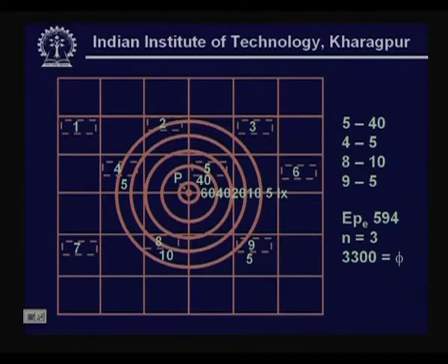Now, from the manufacturer's isolux diagram, we place it. Incidentally, the picture shows the calculations being done at the center of this diagram, that is at P. I place the isolux diagram at P and I get the illuminance levels for various lamps.